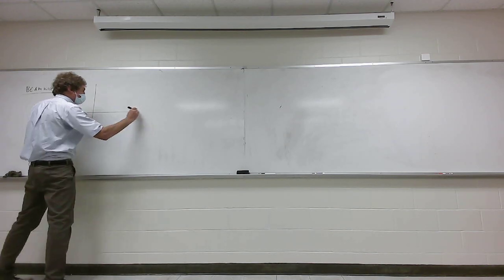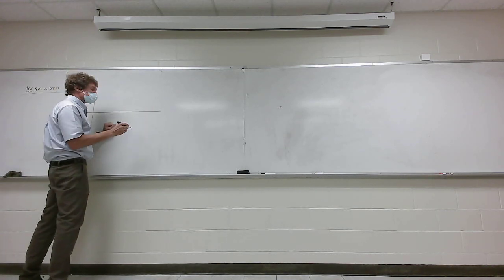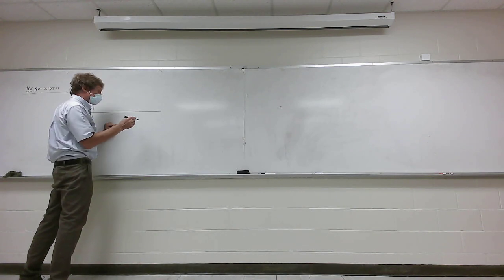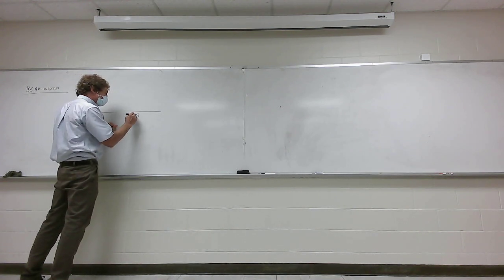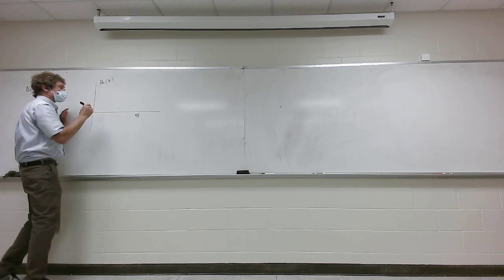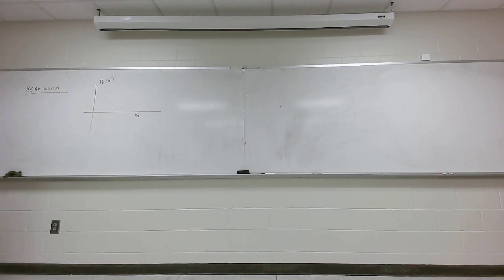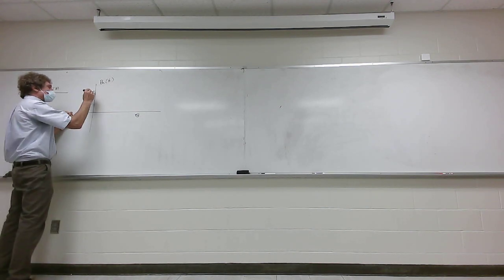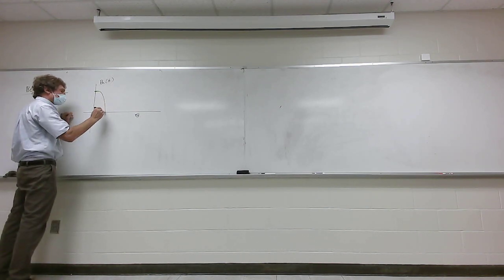usually, not always, if we were to plot this, it's usually not done in the linear domain, but I'm going to do it this way. If this was the angle theta, and this was the normalized power density. Now, normalized power density means it can only have a peak value of 1. Y'all with me on that? For any antenna system, I'm just going to say 1. And if it did this, this would have a value of 1.